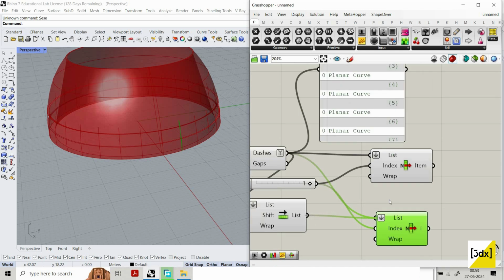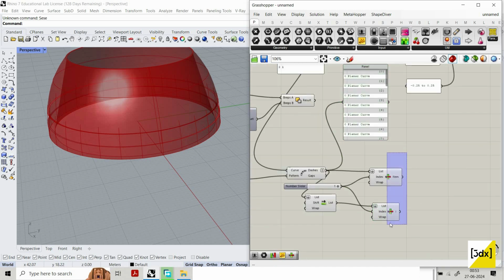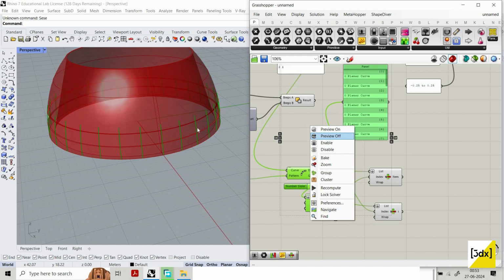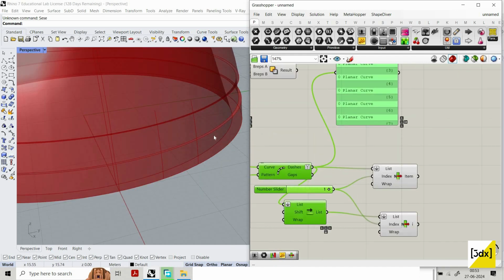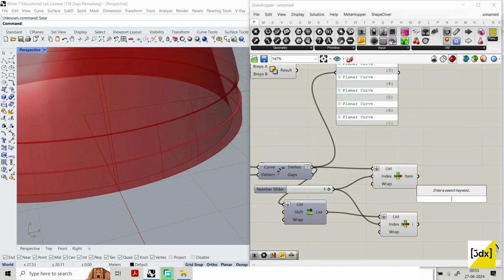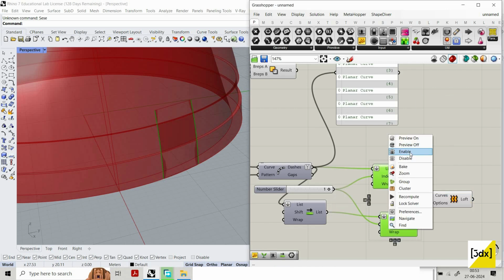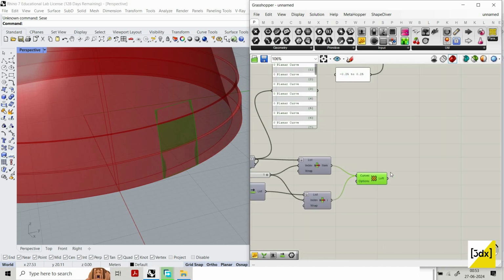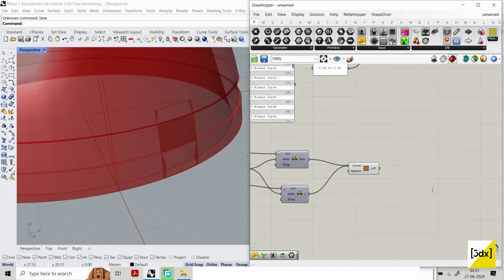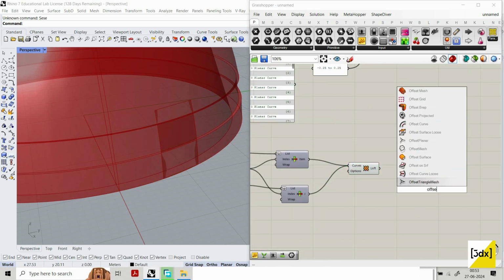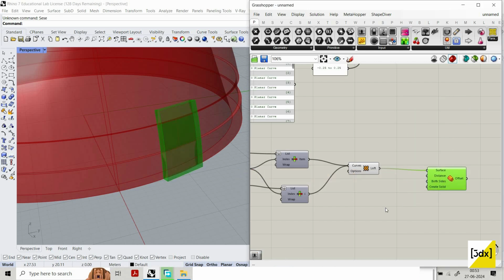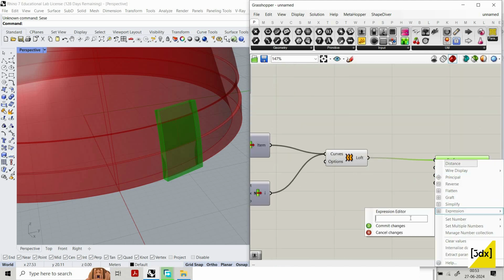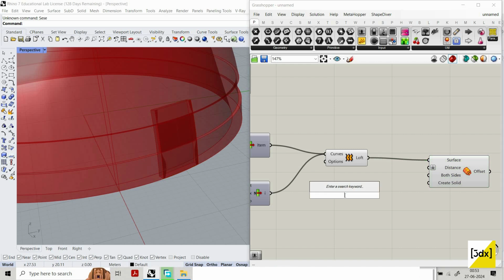And now I'm going to select this so that the list is being shifted, so I can select the nearby curves, and I can create an opening. I'm planning to create an opening for now. Let's create loft and curves. And you see we created the curve. The same concept, offset surface, but I want to offset the input surface, which is easy to cut. Like I'm going to do this as minus x because I'm going to use both sides.